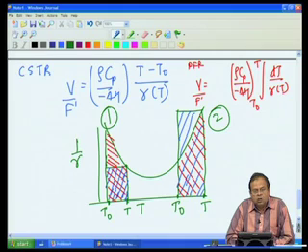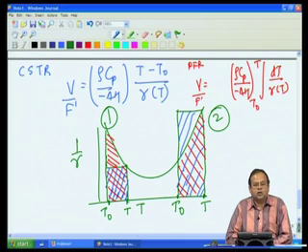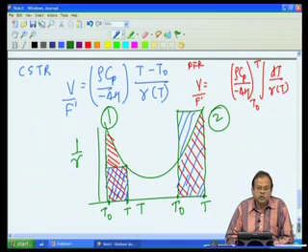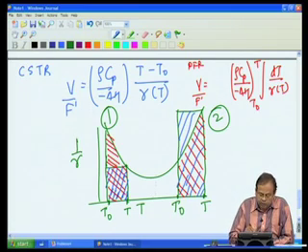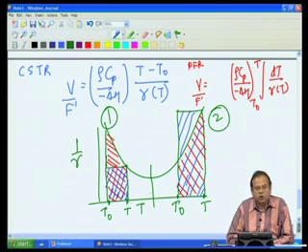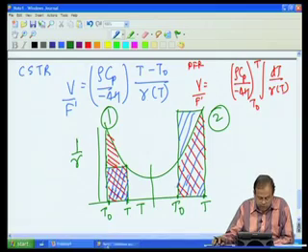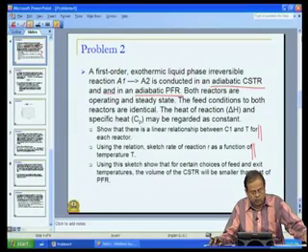I see that if the area under the curve now is smaller than the area of this rectangle, that means the plug flow reactor is better than the stirred tank reactor. So, depending upon our initial choice of starting temperature, if it was up to here, and in fact all those cases where the initial temperature was here or even a little more beyond, we will find that the stirred tank reactor is better. But for other cases, such as the second case, the plug flow reactor will be better than the stirred tank reactor.